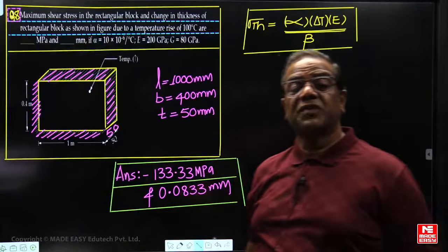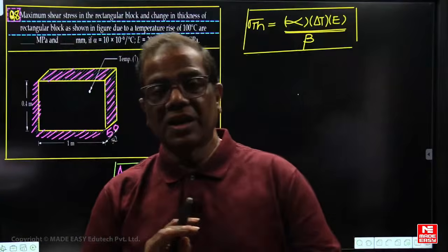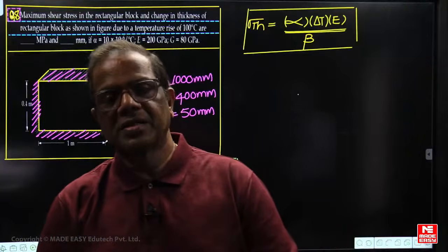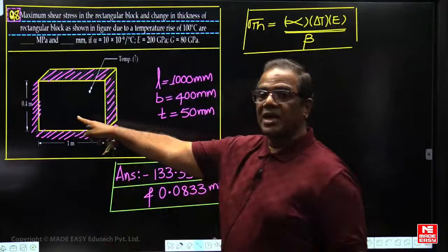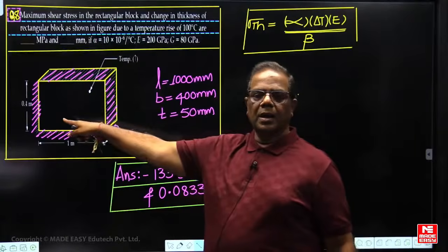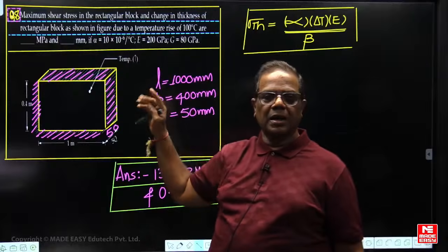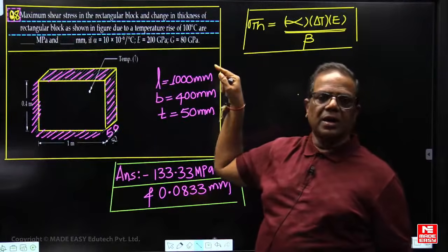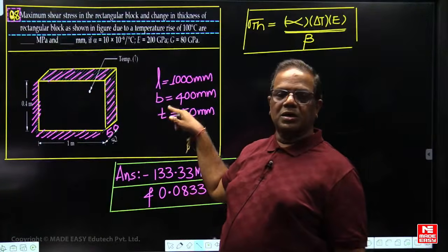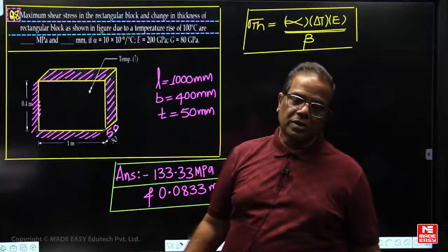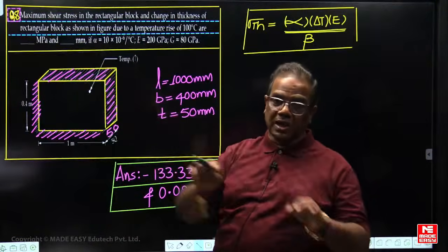This is a generalized equation for thermal stress. This equation I have already given in the classes. Those who remember it can directly give it now. Otherwise, you have to go for the basics now. For the basics, you can equate the total strain in x direction to 0, then you will get the stress. Either equate the total strain in x or y direction. Those who remember the equation directly लिख सकते हैं. But those who are unable to recollect this, अपने basic से करना है.